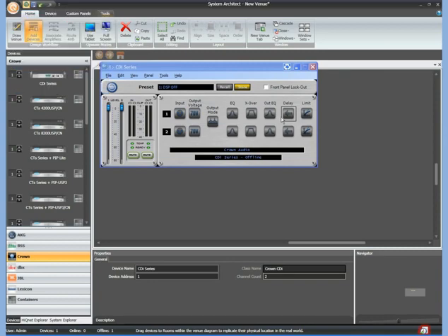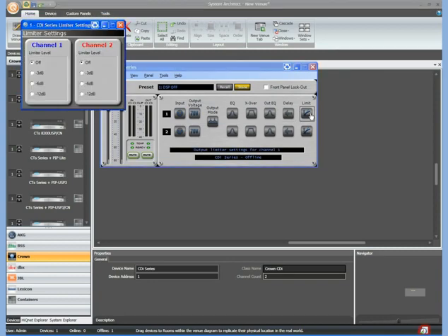And on the output side, we have a very basic limiter. This is a safety limiter. The default is off. I can easily set a 3 dB or a -6 dB limiter. These are fast-acting limiters to catch peaks so they don't blow up your speakers. The JBL Control Contractor Series speakers also have a limiter built in to the crossover to help protect the tweeter. This will help protect the output of the amplifier as well.